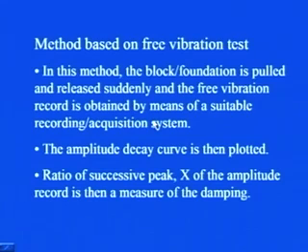Then the method which is based on free vibration test. In this method, the block or foundation is pulled and released suddenly, and the free vibration is recorded by means of a suitable recording and acquisition system.